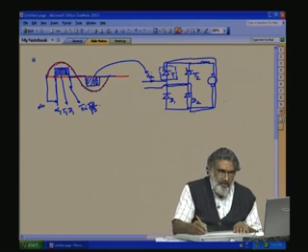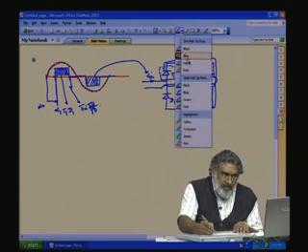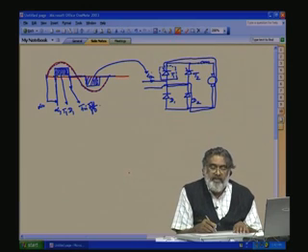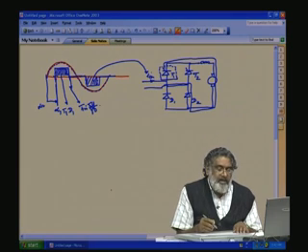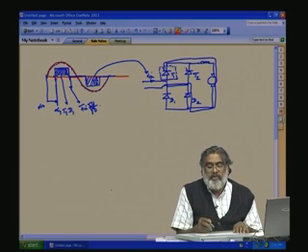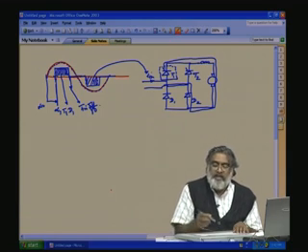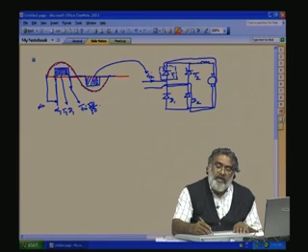This load current is there. Suddenly, you cannot change the load current. So, we should provide some other path for this load current to flow, and T2 is not turned on. The turning off of T1 is not through T2 turn on. We have turned off T1 through some external circuit. We will study one interesting circuit later. But the thyristor will switch off, but the load current cannot die down immediately. If you switch off like that, there is no alternate path, di by dt will suddenly increase, and it will force the current to flow through T1. T1 will not be turned off.